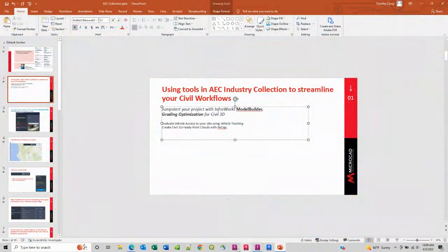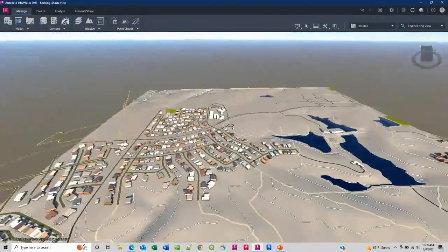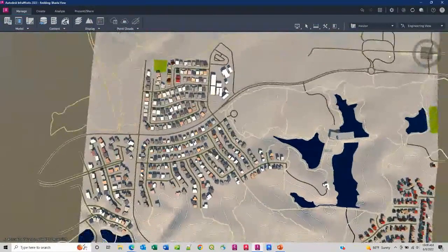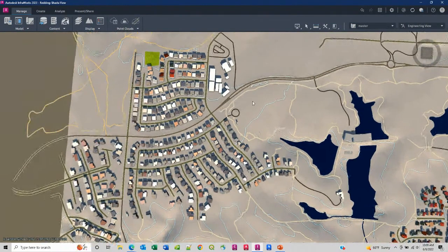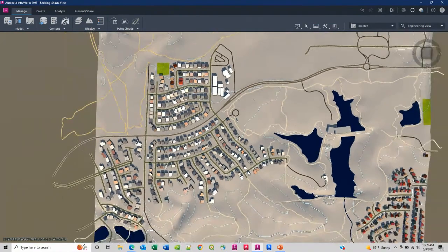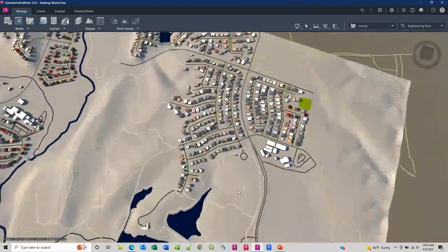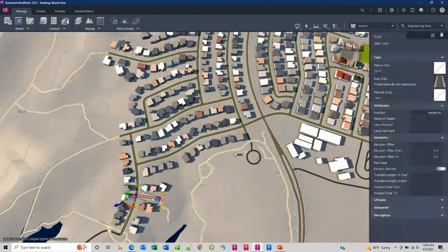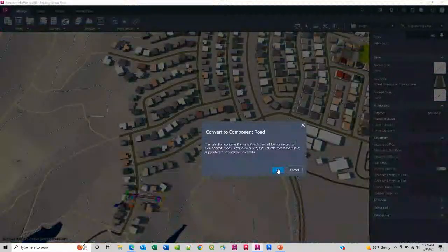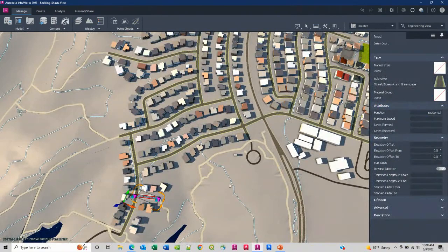Okay, let me look here. Okay, model. Okay, so let's take this now back over to Civil 3D. Okay. So I'm going to go ahead and close this. Now with InfraWorks, oh wait, I want to show you one other thing before I leave here. Just a real quick way to be able to add a road in here and calculate earthworks on that road. So let's say I want to go from the end of this over to here with a little road of some sort that I'm going to sketch in, right?